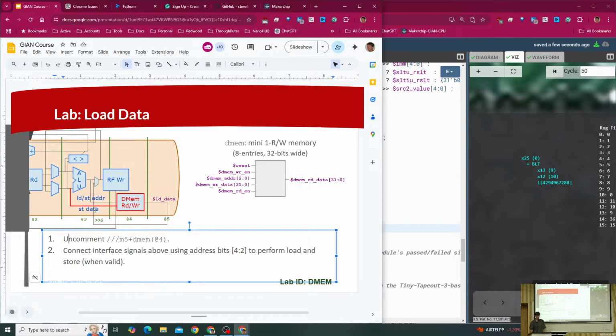So the timing association of the load data that we hooked up is different. Then when we recirculate that into the register file, the recirculation is looking 2 cycles ahead in the pipeline for the load data at stage 5. You're going to get different staging of that data. If we were to assign that as an add 3, that would get staged an additional 2 cycles. It really is associated with add 4. It should be staged just 1 cycle.